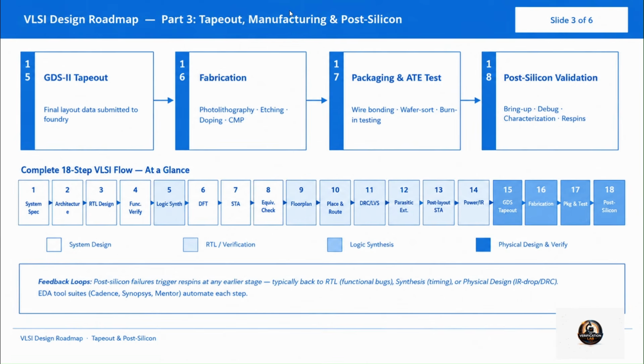In this stage, the actual semiconductor manufacturing process converts the layout into real transistors by using photolithography, etching, ion implantation, CMP, metal deposition, all these things. At advanced nodes like 5 nanometer, billions of transistors exist. The process variation becomes critical.